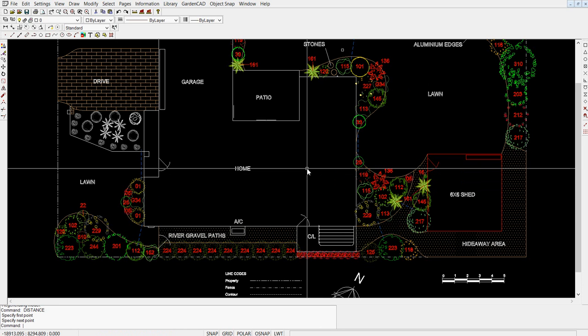So we've built in the computer a full-size model, and we're simply presenting it at some sort of scale in layout space or pages space. There's a scale we use. What I do is make a block of the whole thing and insert the block into paper space. If I inserted a scale of 0.1, that's 1 to 10, 0.01 is 1 to 100, and so on.